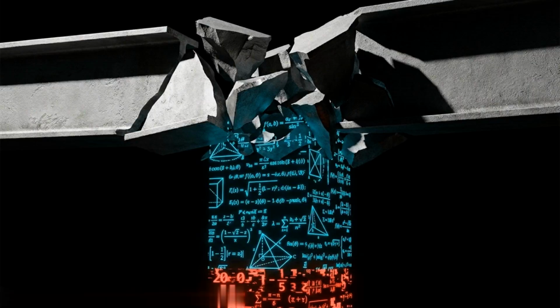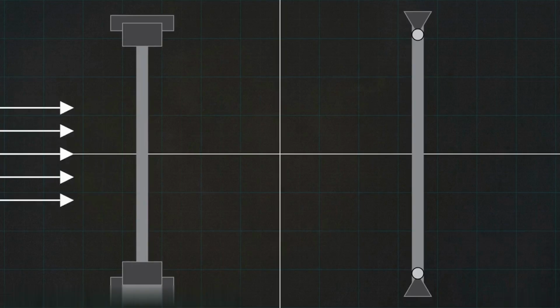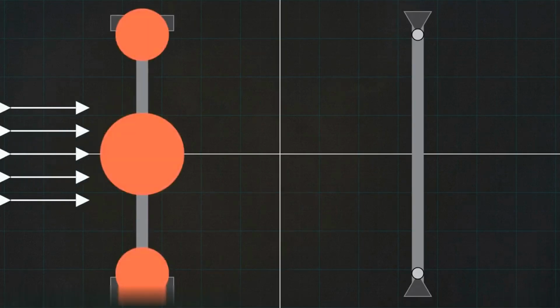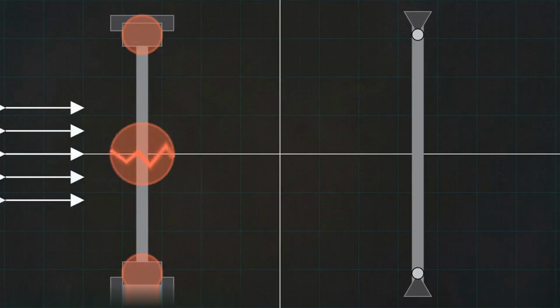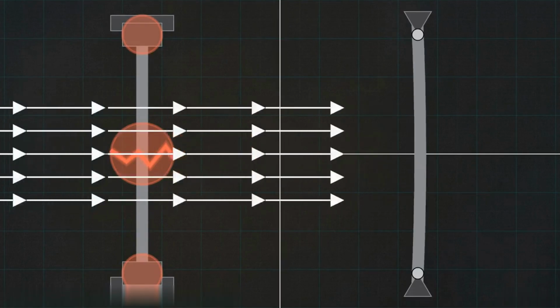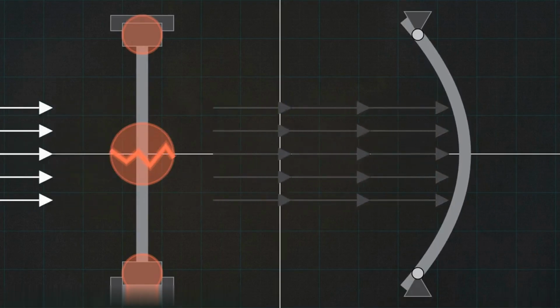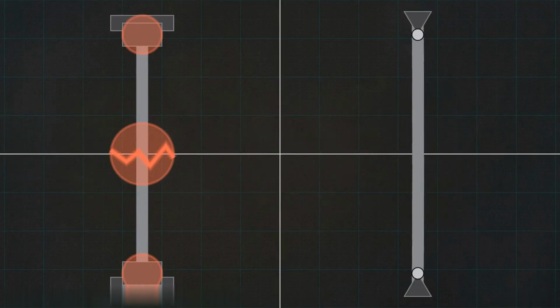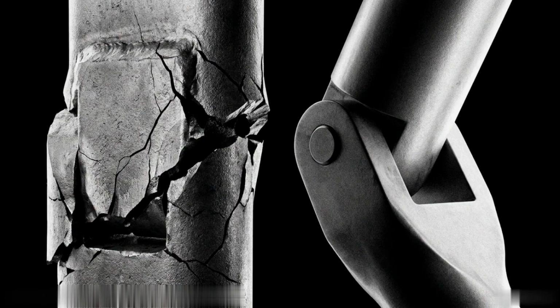The Quebec disaster established a baseline. The incredible tensile strength of industrial steel is completely useless if the underlying vector math is flawed. Engineers eventually realized that fighting forces with perfectly rigid steel was the wrong approach. To survive dynamic loads like gale force winds or heavy traffic, a bridge actually needs to move. Under immense environmental pressure, absolute rigidity leads to brittle failure. Controlled flexibility, allowing the metal to absorb and dissipate the energy, leads to survival.